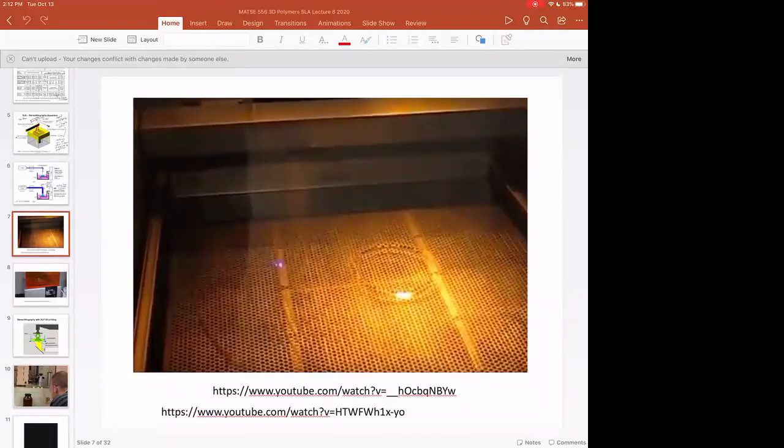When you're working with machines like the ones from this last video, where the laser comes down from the top versus from the bottom, are there any viscosity restraints? I'm assuming that there's going to be a fixed layer height where you have the part, for all intents and purposes, underwater or under resin. So if the viscosity is really high, would you have any surface tension or problems in regulating that? You know what I mean?